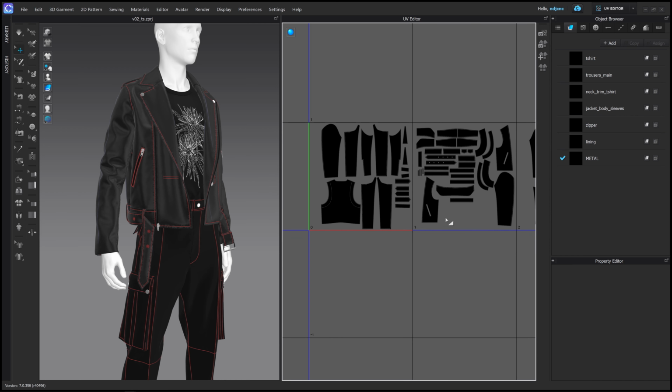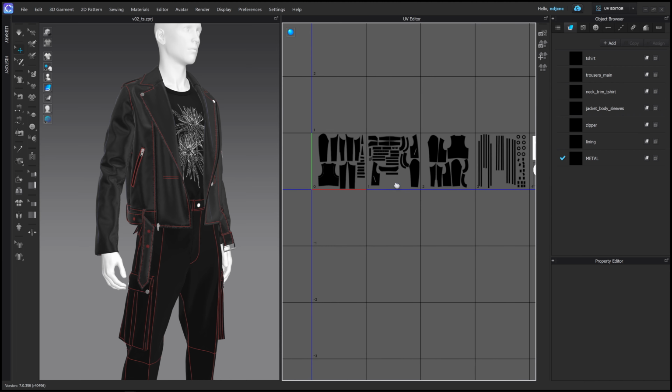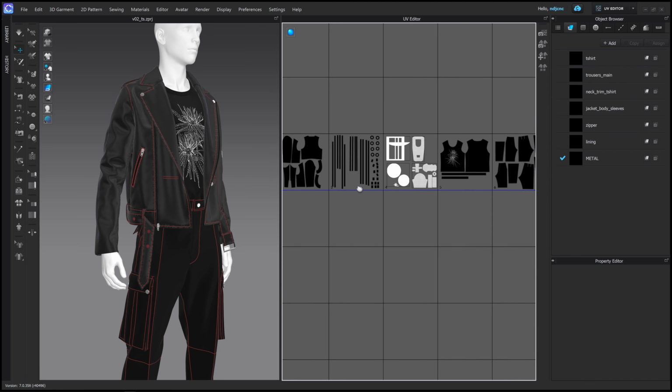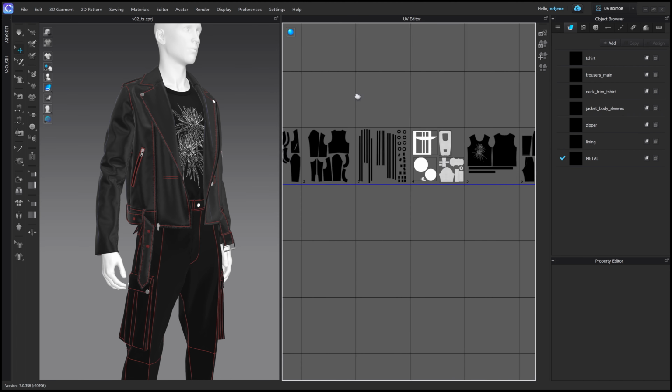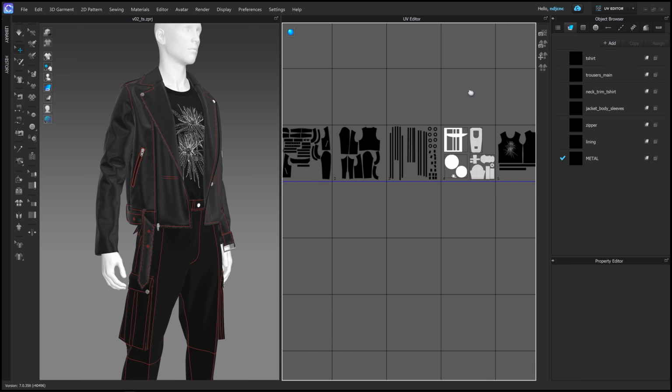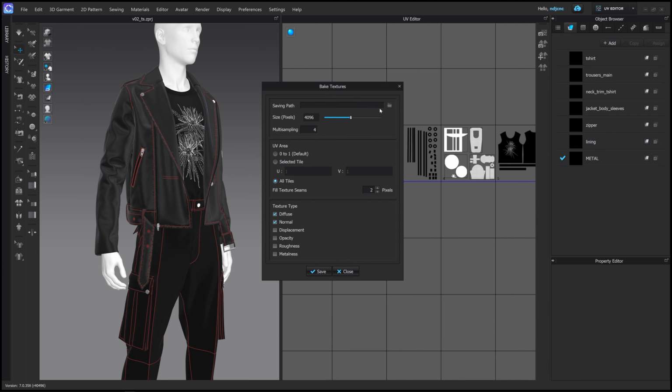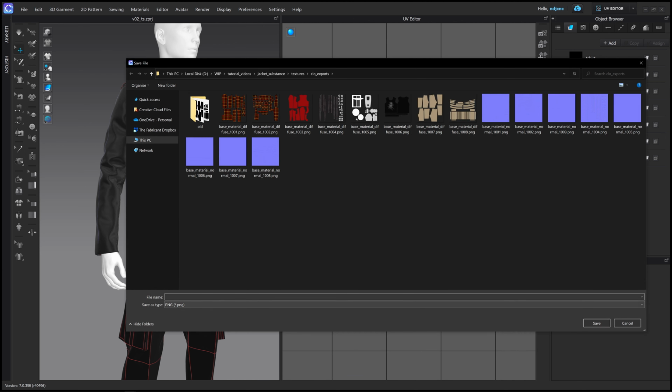And this is going to be a lot quicker to render rather than having each one of these stitches created from geometry. So we want to bake this out, and we're going to do that in the same way we did before. So we have this whole set of tiles of black and white information. I'm going to click the camera icon here, the second one down. I'm going to go to the folder structure from before. I'm going to import stitches as the name of these maps.